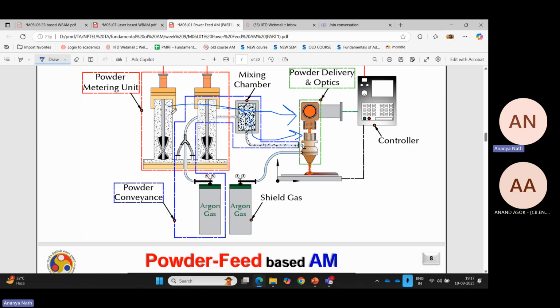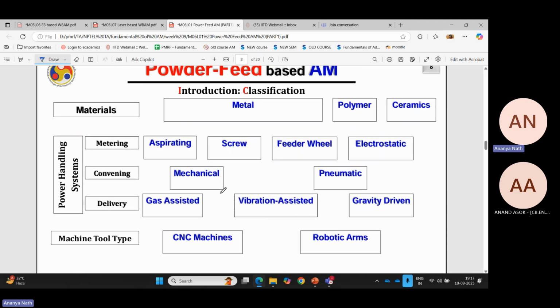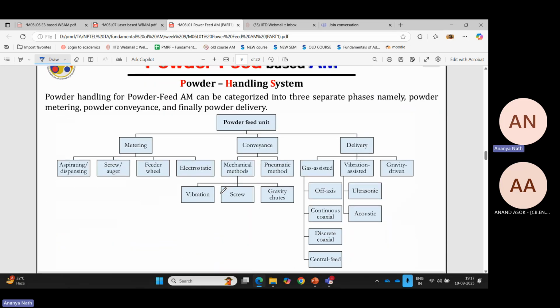Depending on the flow rate, you will have the feed rate of the powder. The powder feeding machine can be of various designs, depending upon which you can fix the parameter, but this argon flow rate will be constant. Next, DED cannot print any polymer. It can only print metal.